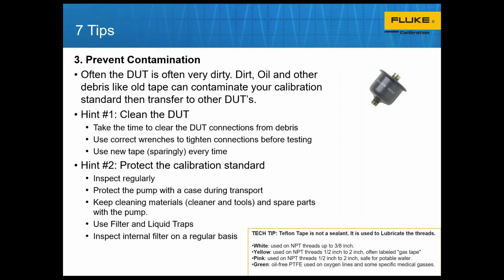This is just a small little comment. If you take a look at the tech tip on the bottom right-hand corner, it says Teflon tape is not a sealant. It's used to lubricate the threads. We have some people that'll have a leaking connection and they'll just wrap it 2, 3, 4 times. They're actually probably not solving the problem, making it more difficult for the fittings to get a good connection because they've introduced too much material between the points where it should be sealing. Again, use the right tape and use it sparingly.